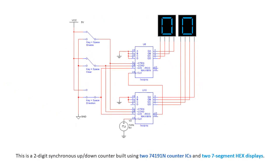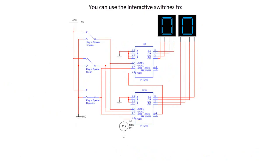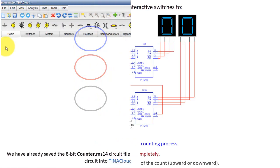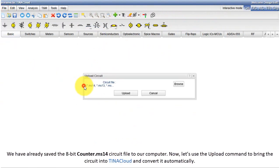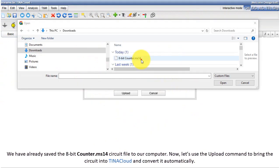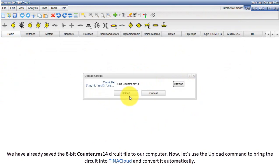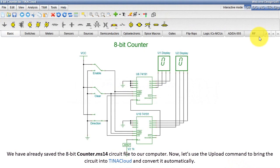This is a 2-digit synchronous up-down counter built using two 74191N counter ICs and two 7-segment hex displays. You can use the interactive switches to enable or disable the counting process, clear the counters completely, and control the direction of the count, upward or downward. We have already saved the 8-bit counter.ms14 circuit file to our computer. Now, let's use the upload command to bring the circuit into TINACloud and convert it automatically.